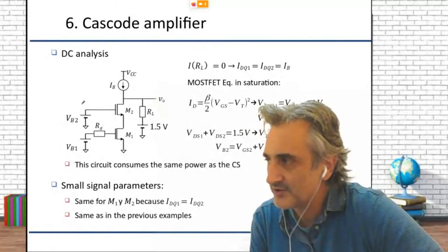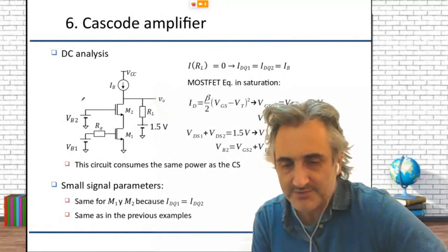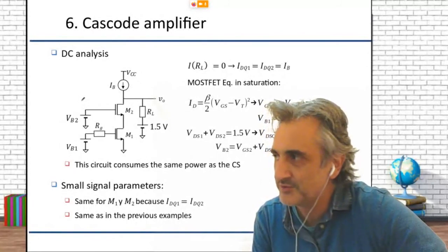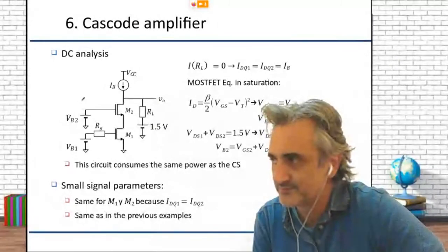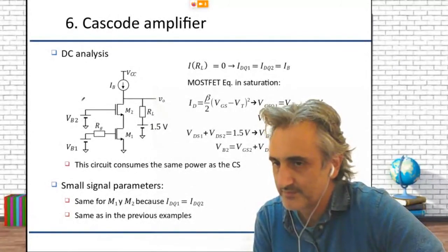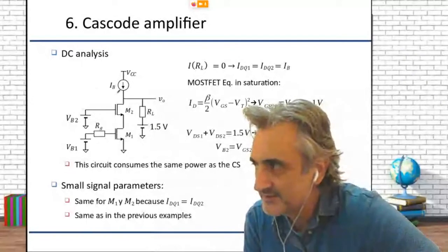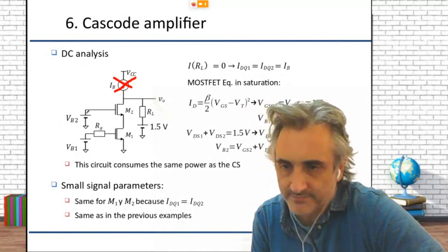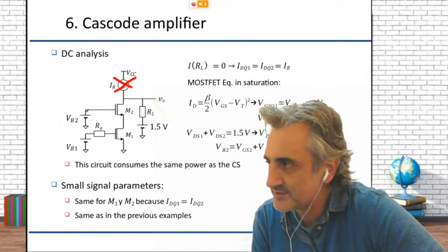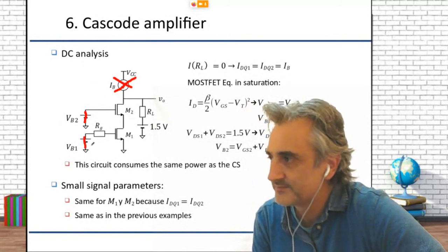First, in order to go from large to small signal, we put the values of all the independent sources to 0. That means 0 current is an open circuit, and 0 voltage is a short circuit.